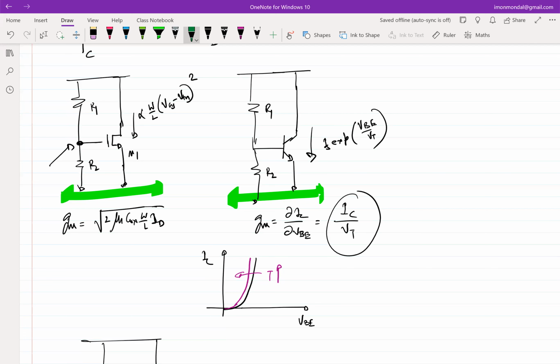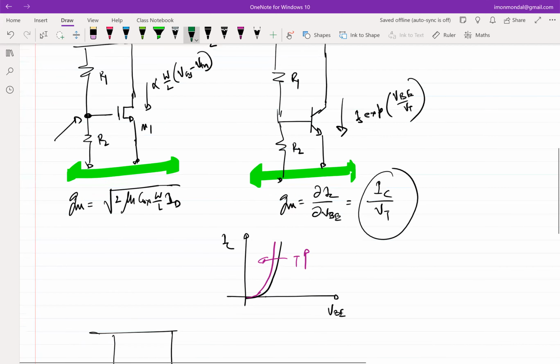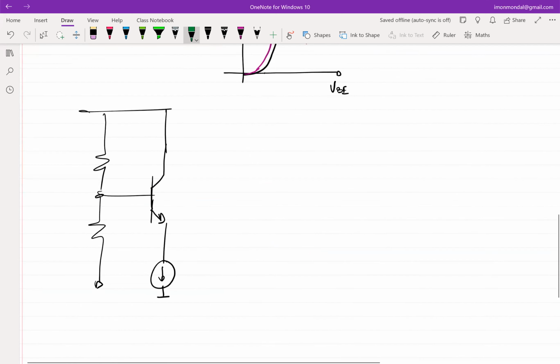However, in case of a MOSFET, it's the other way around. It's an electrothermal negative feedback. It has a negative temperature dependence, which essentially means that if power increases, current decreases. So it quickly balances out. So there is an electrothermal negative feedback loop in a MOSFET, but it's a positive feedback loop in case of a BJT. Having said all of this, the solution is pretty simple: bias it with a constant current source.